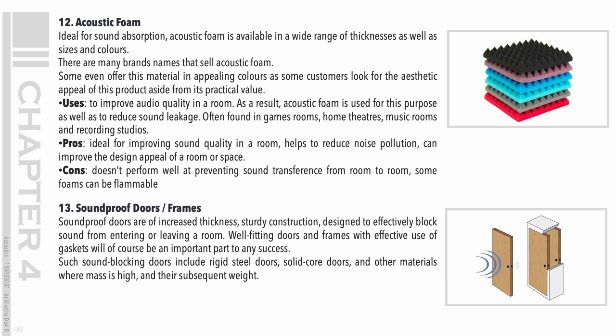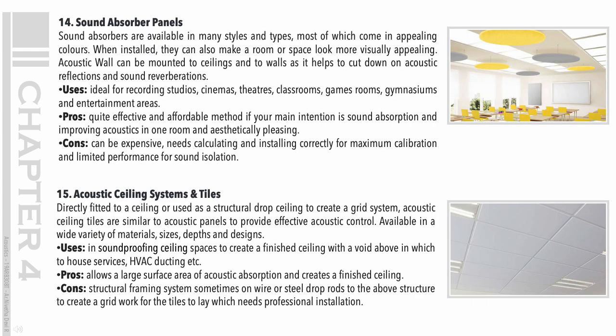13. Soundproof doors, frames. Soundproof doors are of increased thickness, sturdy construction, designed to effectively block sound from entering or leaving a room. Well-fitting doors and frames with effective use of gaskets will of course be an important part to any success. Such sound-blocking doors include rigid steel doors, solid core doors, and other materials where mass is high, and their subsequent weight.